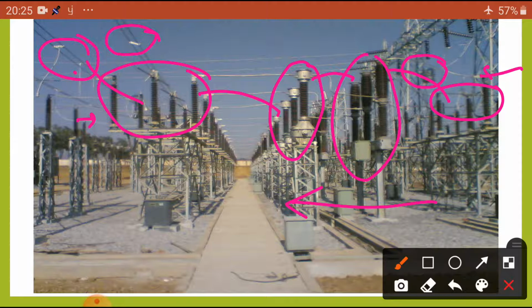Okay. So if any problem occurs in the CT, for repair purpose we are going to isolate any equipment with the help of the isolators. With isolators we can physically see whether the circuit is open, whereas in circuit breakers we cannot see that. So that is the problem. When the circuit breaker is closed, if a malfunction occurred, what will happen? There are dangerous accidents. To avoid that, we are going to use isolators in each section.